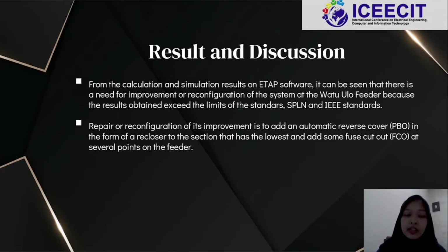The improvement or reconfiguration is to add an automatic reverse cover, or in Indonesian penutup balik otomatis or PBO, in the form of a recloser to the section that has the lowest reliability, and add some fuse cut out or FCO at several points on the feeder.